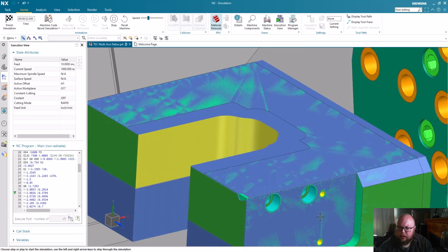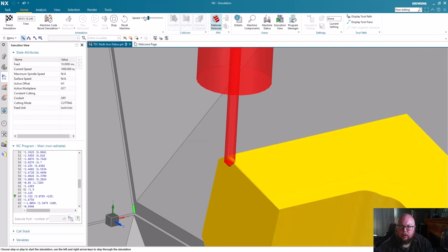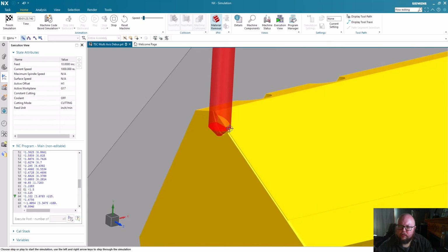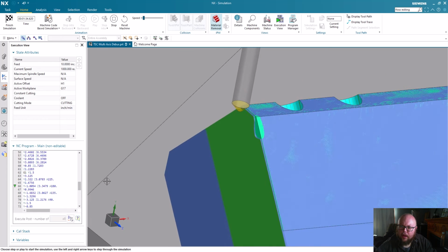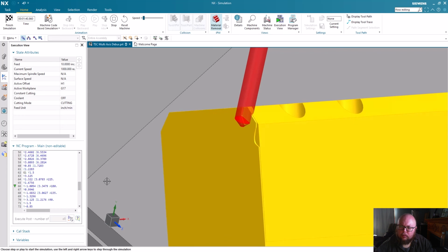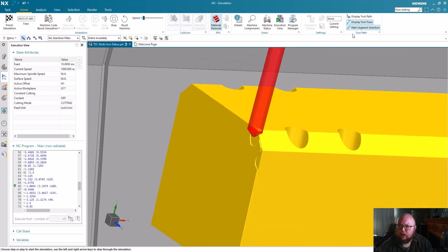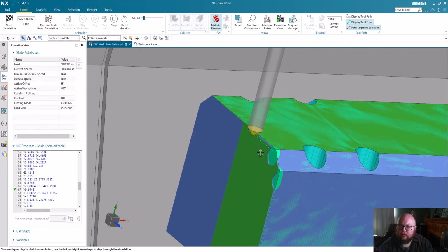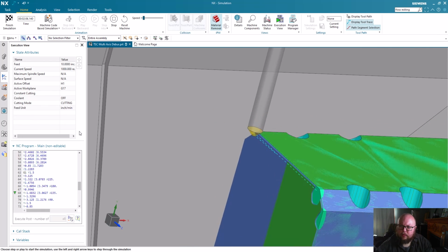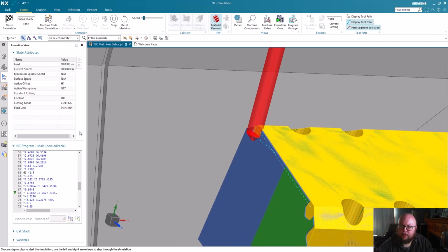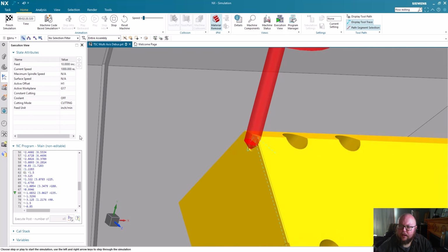You can see that gouge left behind. You can see the tool is pretty deep into the part. Definitely not something that you would want to have happen as you're running your part. But again, if we display our tool motions as we're coming up to this next corner, you'll see that this motion certainly does not represent what we saw inside the actual operation.